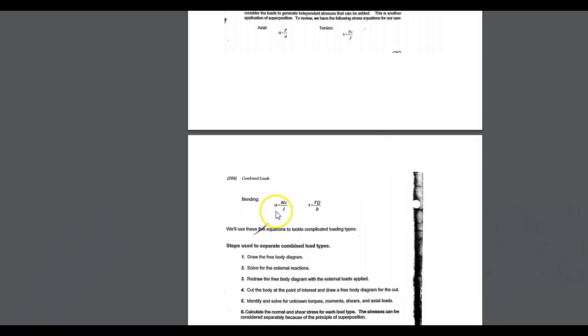When we do shear moment diagrams, we have different values of V and different values of M across a structural member. Another one is if we have some sort of a combined load where in the past we've had a column of two different diameters that's extruded from a ceiling, and we have a load at the end of the entire apparatus, and then we have a load maybe where the two pieces of the apparatus are welded together, so that the P in one section is different than the P in the other.